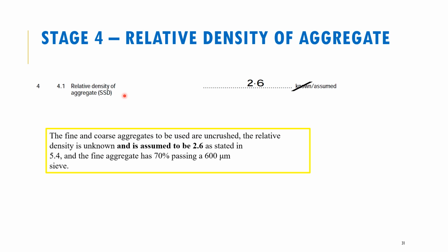There's no water on the surface. Any water that's present is present inside the actual aggregate. So the best condition for an aggregate is to be at the SSD stage where it's saturated from the inside but dry from the outside.